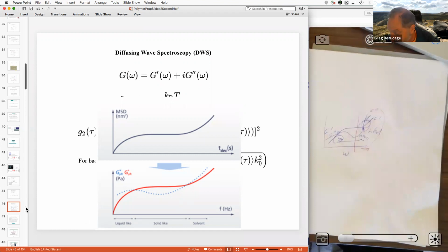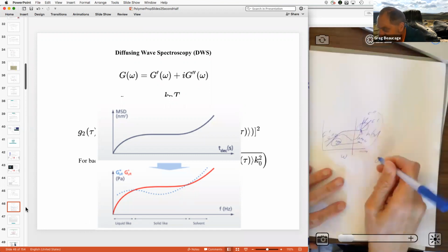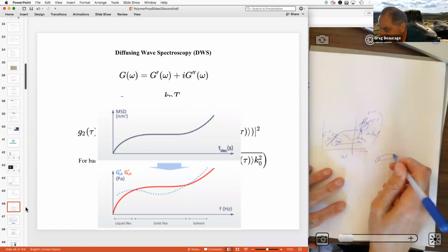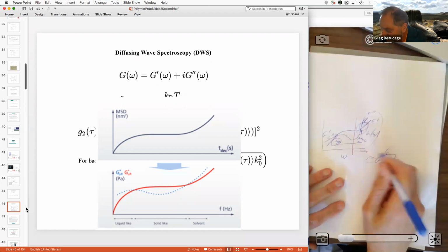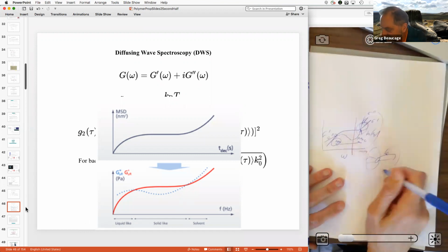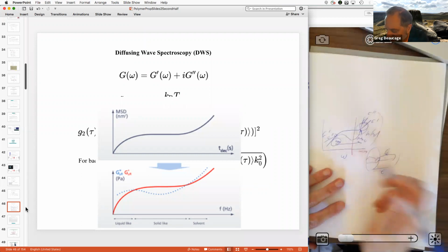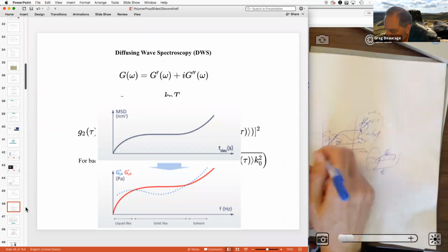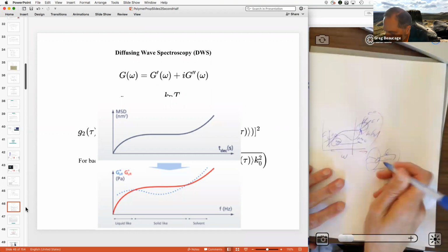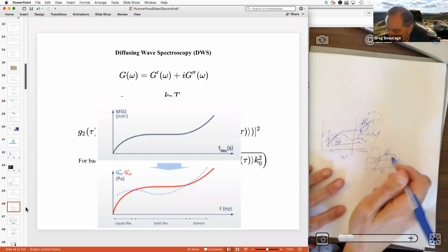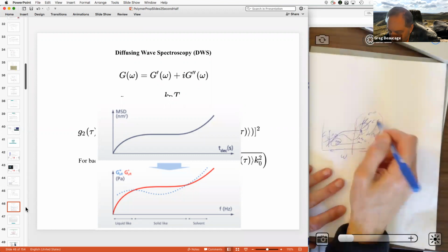Because if you want to model the rheology, the flow of something like polyethylene, you have to start somewhere, right? And the place you want to start is the Kuhn unit, right? You want to start at least at LK, if not below. Then you hook up the Kuhn units, and then you want to see the tube diameter. So you're putting together a model with these pieces in it, so you can talk about the bulk viscosity out at really low frequency. But you have to start with the high frequency response and then build it up. If you don't have measurements out here, you can't do that.